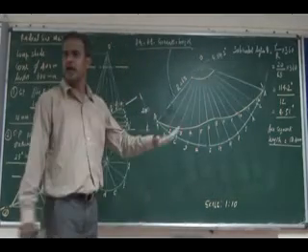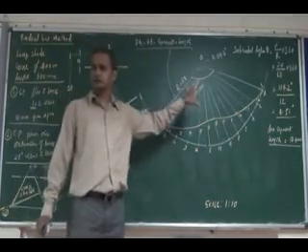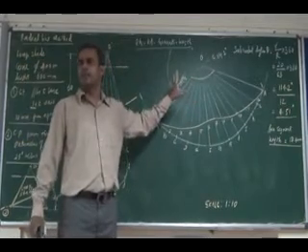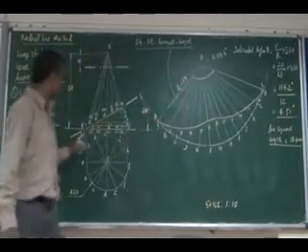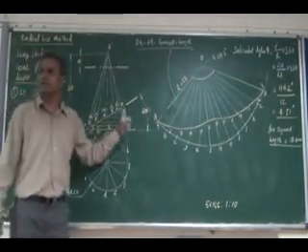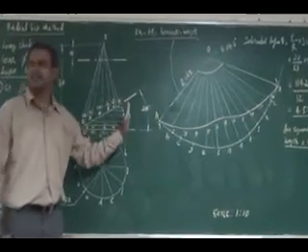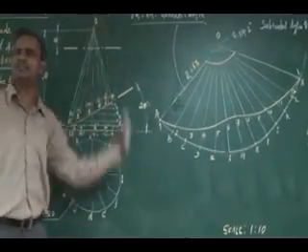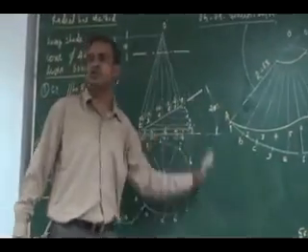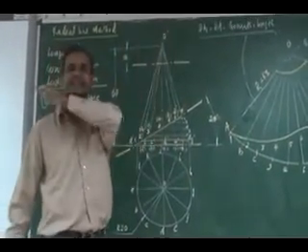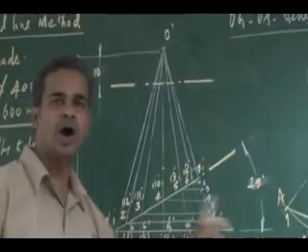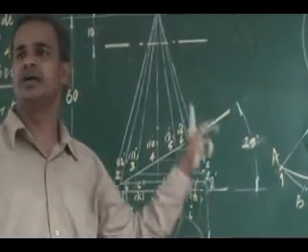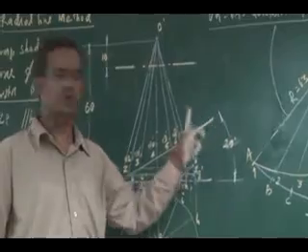Listen again. This is important: how to transfer the cutting points in a cone or pyramid. The cutting point has to be transferred to the extreme generator, since only the extreme generator shows the true length. All the points have to be transferred to the generator showing true length.